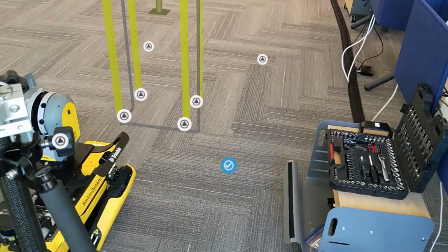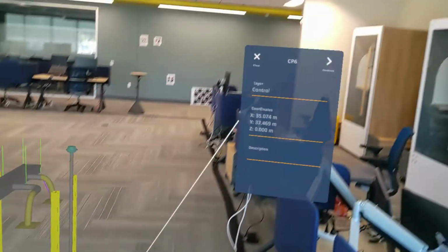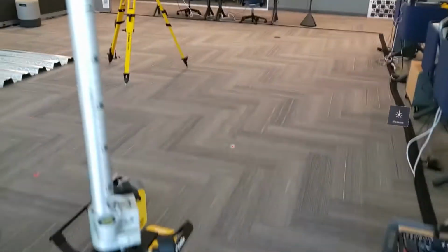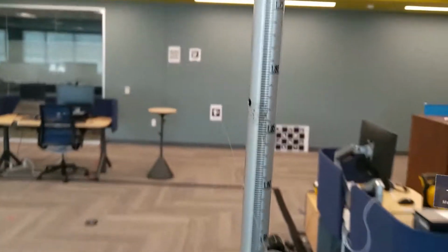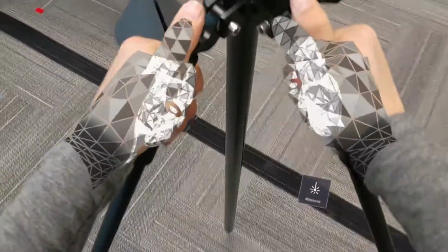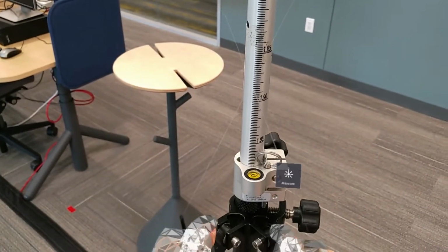Now, when we select our control point for the station setup, we hit the Continue button once we've confirmed we've picked the right point. After doing so, we'll see our total station measure button show up, and it'll follow us where we go. Now we need to physically navigate to our position on the job site and position our prism pole or aim the laser using the joystick tool onto the control point.